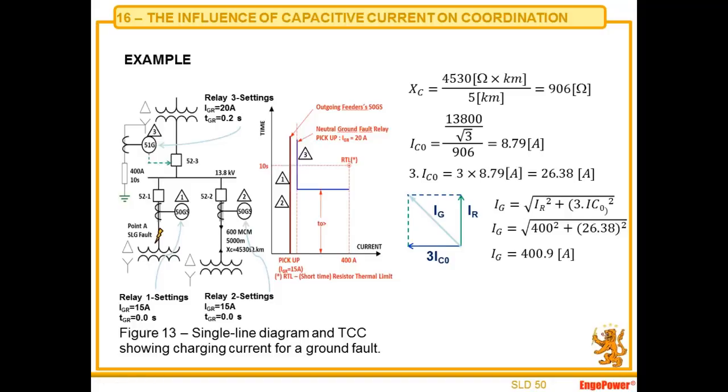Here there is another piece of knowledge also. Neutral resistor. Normally, if you don't declare to the manufacturer what's the permanent continuous current that this resistor shall be able to carry, the manufacturer will say that it's 0.